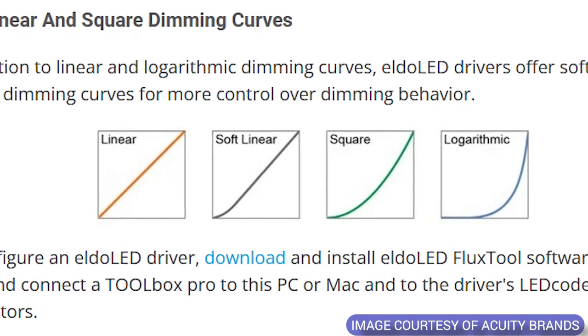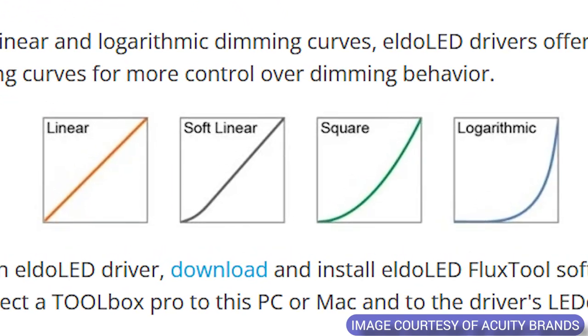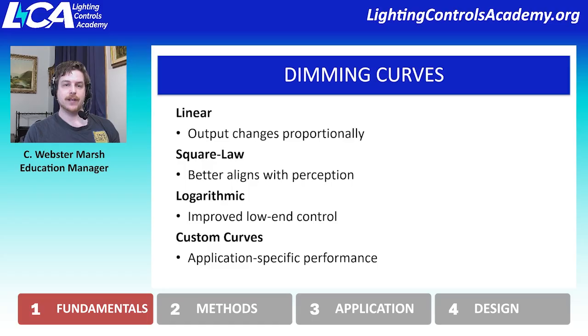It might be color-specific, where we picked one color and we're trying to fade to a different color, and in between those 2 points on the color graph is a really ugly color, so we create a custom curve for those colors. But custom curves really do provide much more specificity to dimming capabilities and may not be appropriate for every application. And so typically we see either linear or logarithmic being applied to standard static white interior spaces.